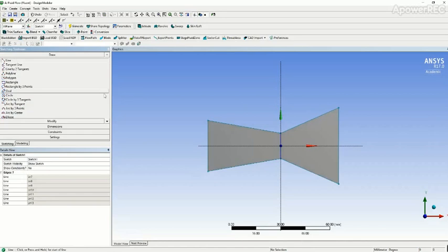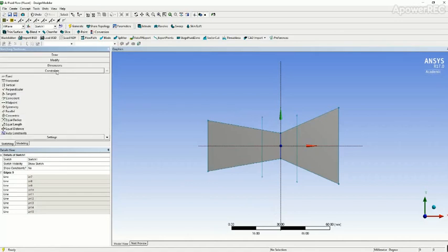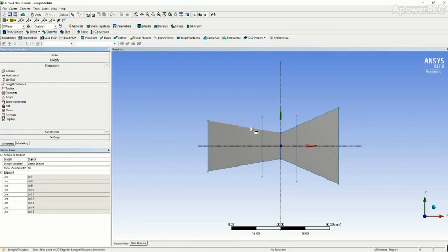Now we will further split the parts, for which we draw a line again, two parallel lines. To make them parallel lines, we use a constraint called parallel, to parallelize the lines. Once we parallelize the lines, we input the distance. We want to keep it equidistant from the middle line. So we're going to take both the distances to be about 10 millimeters approximately.